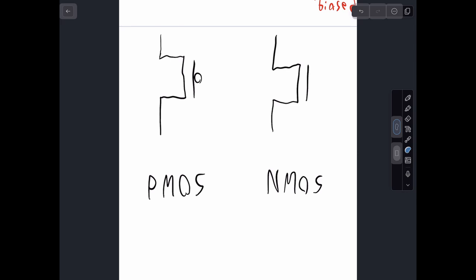0. Yeah, well, not quite, right? Because technically there's going to be a small capacitance to the earth, to just everything. So actually it's going to be charged to some unknown value. It's either going to be 0 volts or 1 volt, could be 1,000,000 volts, could be anything. So actually we don't know what this voltage is.